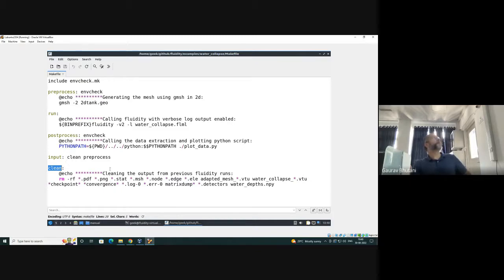Now what we'll do is run pre-process. Pre-process creates a mesh from a geometry, because for using FEM, we need to create those meshes having elements. Those triangles here for 2D. In 1D, we have simply line elements. Because remember, we have to define those shape functions over these meshes. So rather than writing this complete command, we'll simply run pre-process with make to do something interesting.